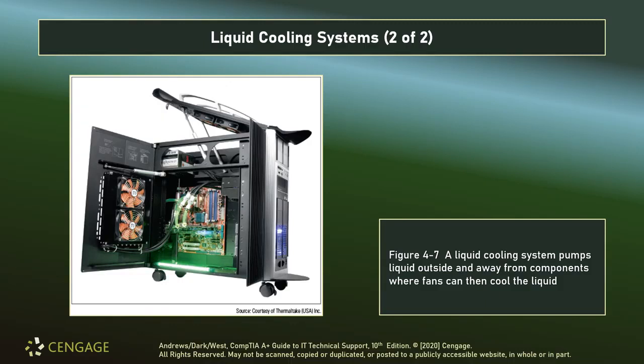Now once the coolant has come into the reservoir underneath those fans, what we want to do is make sure that the air bubbles are to a minimum. Air doesn't transmit heat very well. If we look at convection, molecular motion in general, we do better with liquids than with gases, and better with solids than with liquids. So that's why we have the big aluminum block on the heatsink, and that's why we have a very dense fluid, such as antifreeze or something similar, inside of a cooling arterial system like this.